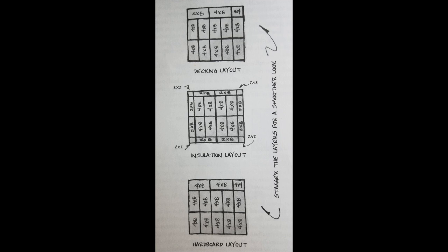Again, like the orientation of OSB, you want to have it alternating directions. And one of the reasons for this is that in the end, this alternating pattern allows you to hide the seams from the piece below. This is important because it's not always 100% accurate whenever you put two platforms together. There may be a gap or something that is out of your control to fix. And so having these alternating layers allows you to hide those as best as possible.